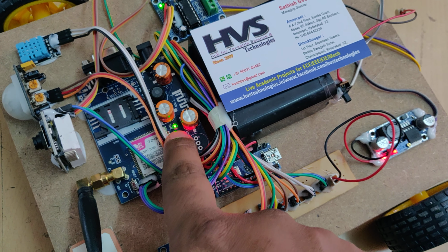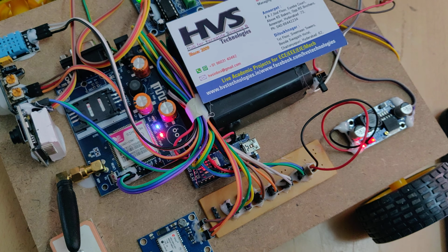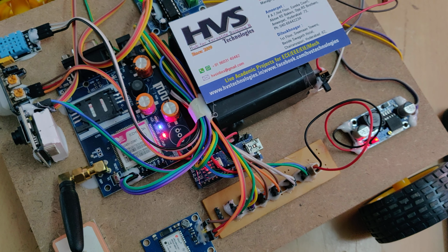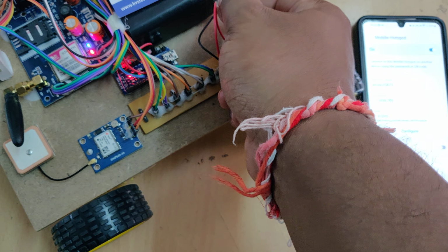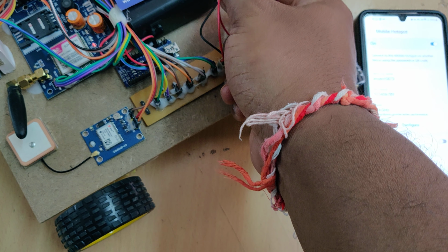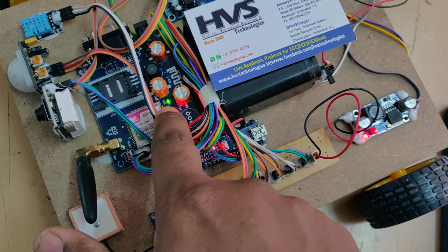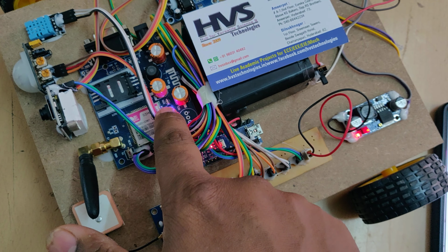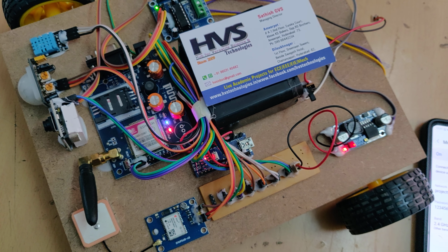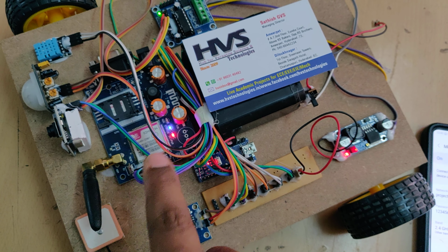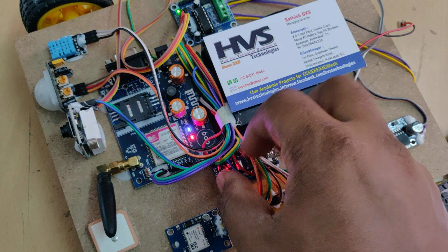So when we turn this on initially, this particular green light will turn on and off at a duration of 1 second. On successfully getting the signal, if it is not showing on the mobile phone, just turn it off and on. Right, we connected, and now check this GSM modem. The next step is, it has to blink slowly. Till that, wait. Its blinking rate is 3 seconds per blink. Now the GSM modem got the signal, and we can cover the PIR sensor